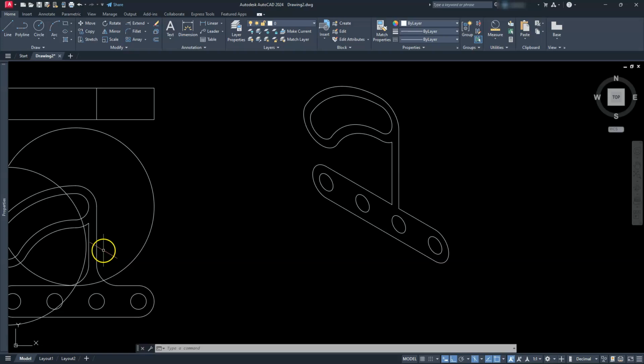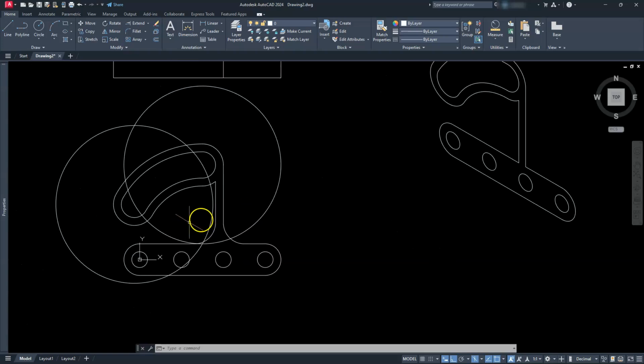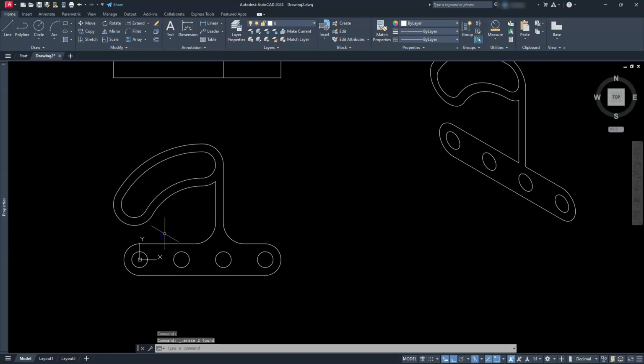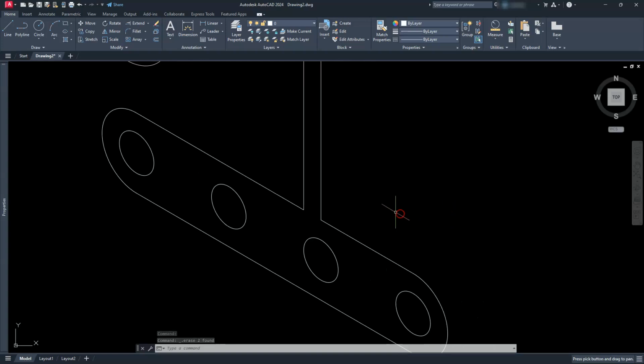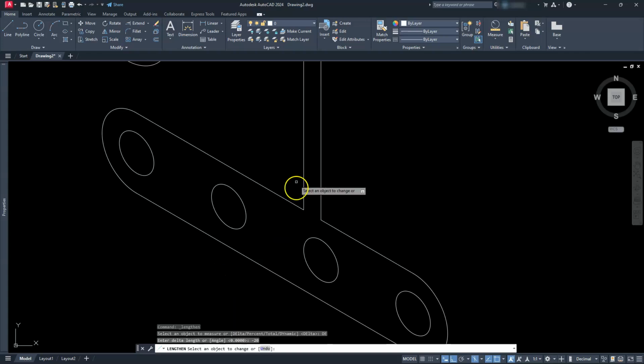go ahead and put those on here in a second. Right? So we do have those two comparisons that are happening. Let's go ahead and delete those. We don't need those anymore. All right. So to go ahead and work our fillets here, I'll use the lengthen command. Choose delta, -20. And I'll go ahead and select these lines here. So that one, this one, this one, and this one.